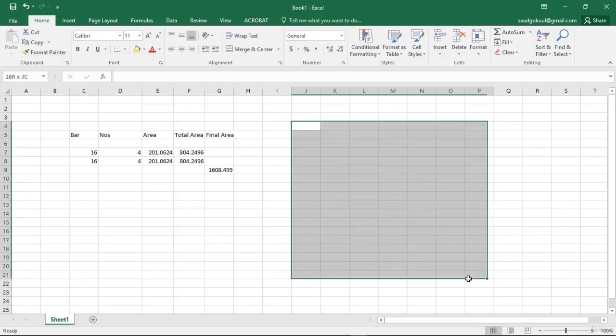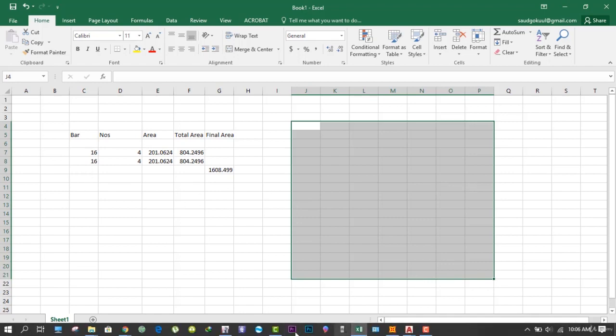Now suppose that this is your column, and we have to provide 8 numbers of 16 mm bars. So what we do, we provide 1, 2, 3, 4 at the corners, and 1, 2, 3, 4 at the mid portion, right? So this is how you detail this column.